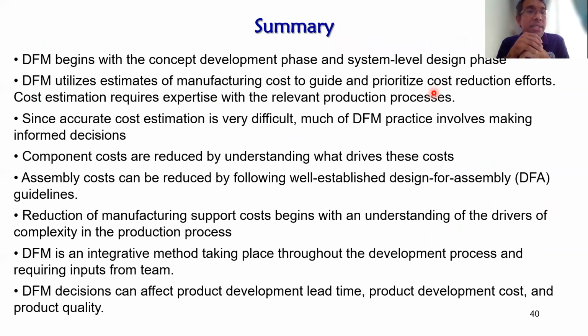So for the summary, DFM begins with the concept development phase and the system level design phase. DFM utilizes estimates of manufacturing cost to guide the prioritized cost reduction effort. Cost estimation requires expertise with the relevant production process. And since accurate cost estimation is very difficult, much of DFM practice involves making informed decisions.